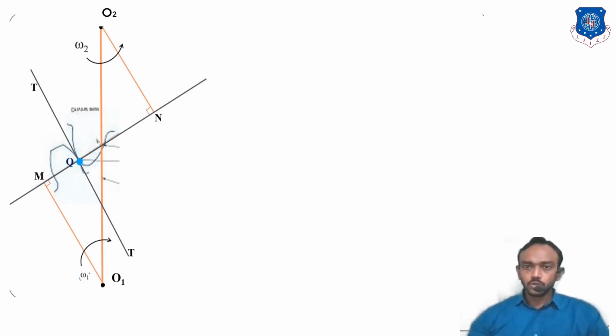Q is a point which can be considered as belonging to gear 1 and gear 2 both. So we can connect the contact point Q to gear 1 and gear 2. You can see that the lines QO2 and MN make an angle, and the same for O1Q and O1M.